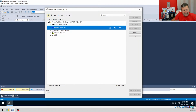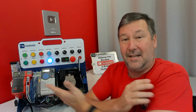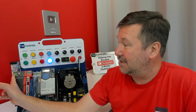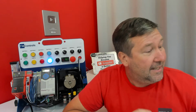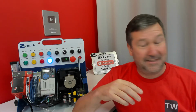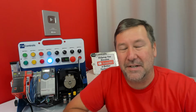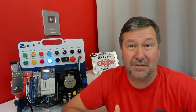So now we need to know a little bit about IP addresses. First of all, we've got to know what is the IP address of the PLC? And what is the IP address of our computer? With the Compact GuardLogix, it does display it across it. If you wait long enough, it'll finally scroll across. Now, that doesn't help us any on this CompactLogix PLC, and it doesn't help us any on this MicroLogix PLC. So we're going to need to inventory our networks. We need to know before we ever start connecting to a plant network what all the IP addresses are.